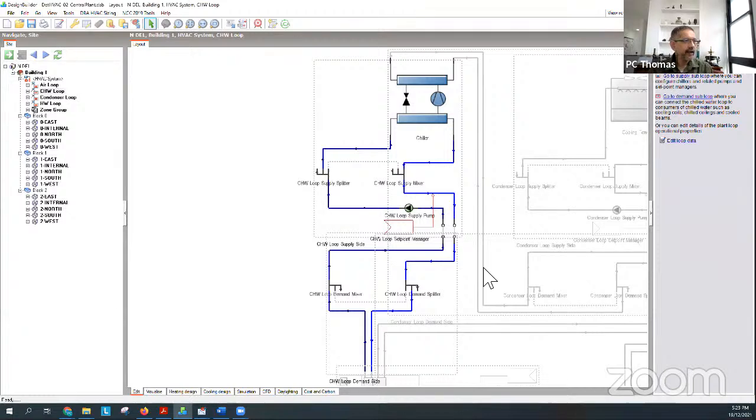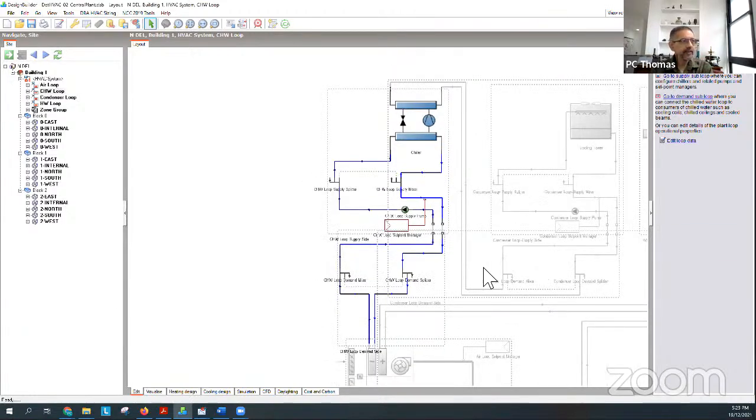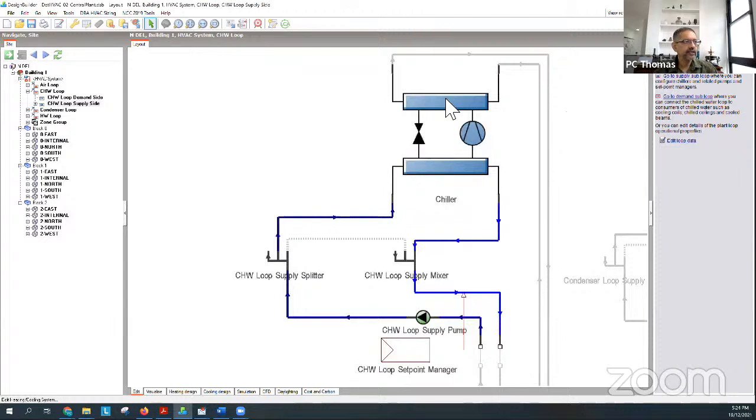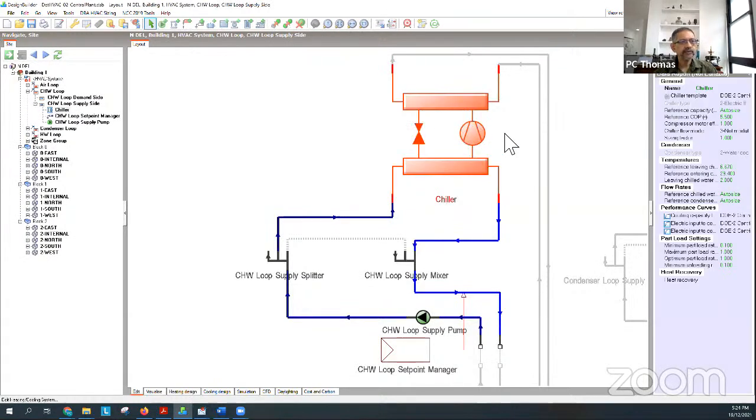Okay. Now, what I wanted to show you is how to put a twin chiller plant, because typically when you're using centralized systems, you have a multiple chiller plant room. If you have only one chiller, generally you haven't got to a size where that is efficient. When you get to 1,000, 2,000 kilowatts requirement, then you need multiple chillers. So first I'll just check the description for the chiller itself, and I just want to edit that chiller and see that everything is appropriate.